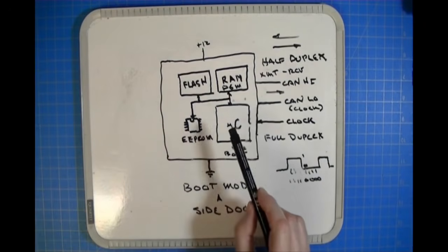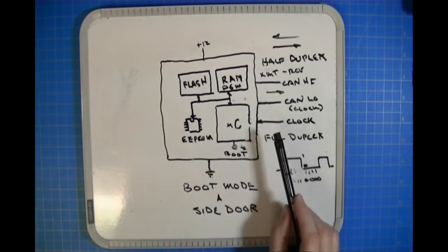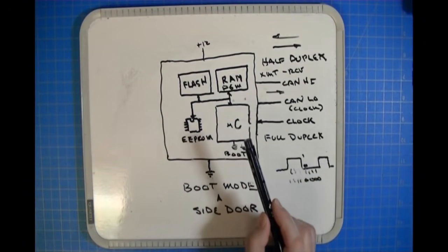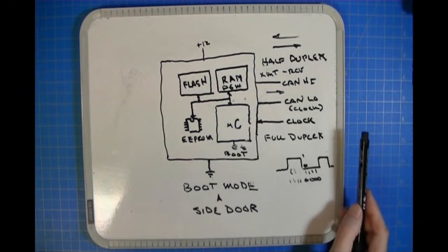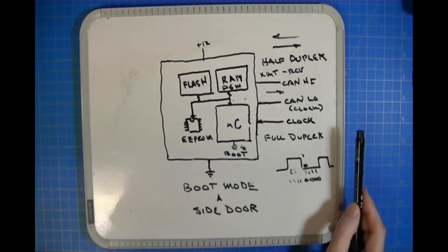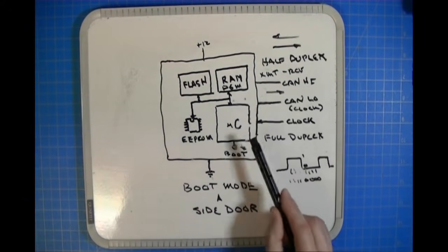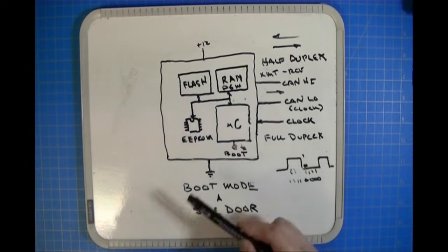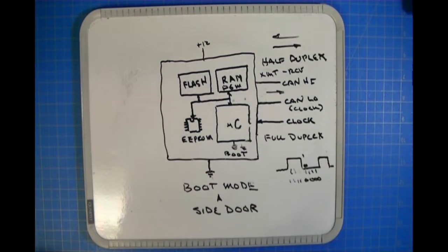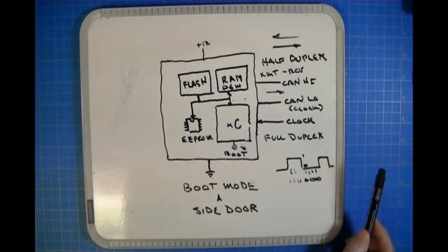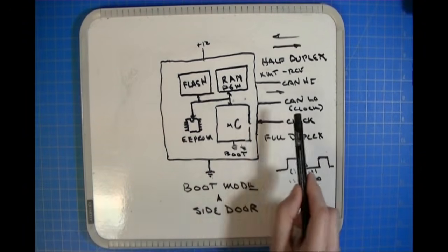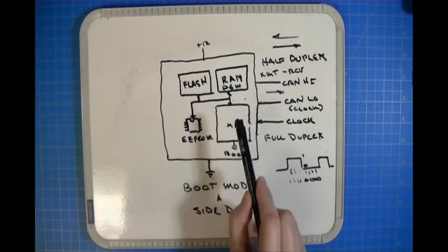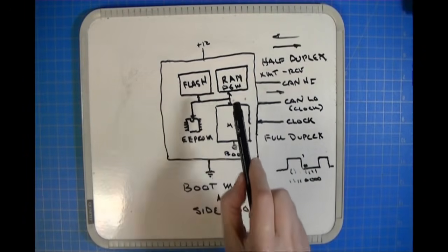Believe me, there's a bunch of different options for engineers to choose in the microcontroller. But fundamentally, when it's in boot mode, after it enters boot mode, you're going to take the ground pin away, and the processor's going to be sitting there waiting to do something, waiting to get that data coming in. And then the data comes in from the program that's in the tool. It goes into RAM, and after it's all loaded up, the microcontroller then starts executing the program from RAM.